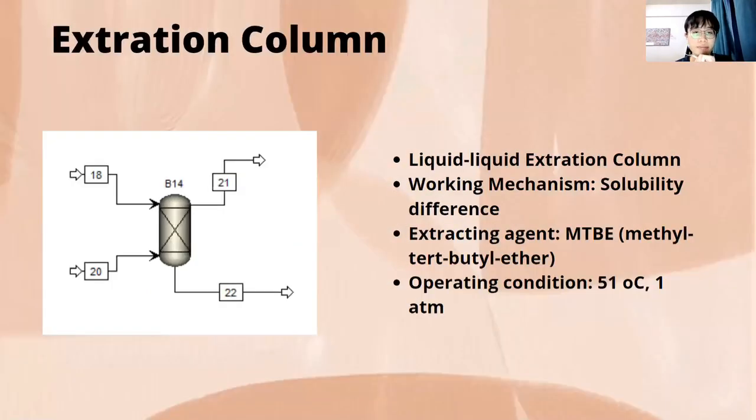Okay, next. Now is the extraction column, which is also known as the liquid-liquid extraction column. It's used to separate compounds based on their relative solubilities. The technique selectively dissolves one or more compounds into an appropriate solvent. The solution of these dissolved compounds is referred to as the extract, while the aqueous phase is referred to as the raffinate.